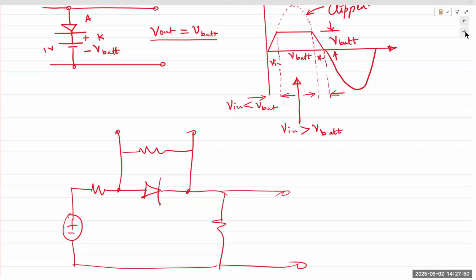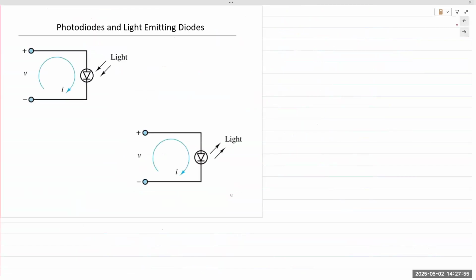All right, the last one is photodiodes. Photodiodes, as the name suggests, have to do with incident photons. Technically, any diode which is interacting with photons is referred to as a photodiode. But in general, photodiodes are the ones where photons are the input. Any kind of electronic device is affected by heat and light. In the fundamentals of semiconductors, we learned that as temperature rises from absolute zero, thermal energy is available for electrons to break their bonds and become free charge carriers. So at room temperature, there are generated charge carriers that are free to conduct.